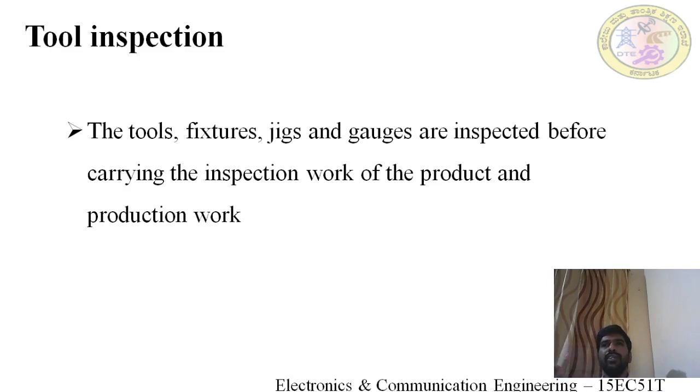See, that is tool inspection. Before doing the actual inspection work, whatever tool, fixture, jig or gauges you are going to use, you need to find out whether they are working or not. This is called tool inspection.